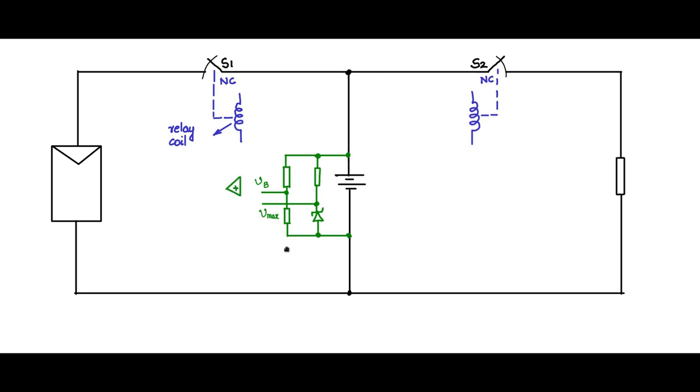Now both of these you buffer with an op amp. So let me pass VB through a buffer. This is a voltage follower, and Vmax also I will buffer. The reason you buffer it is that input impedance is high and output impedance is low, so any resistance that you use will not affect the output side portion of the circuit. So now these two I will give to a comparator.